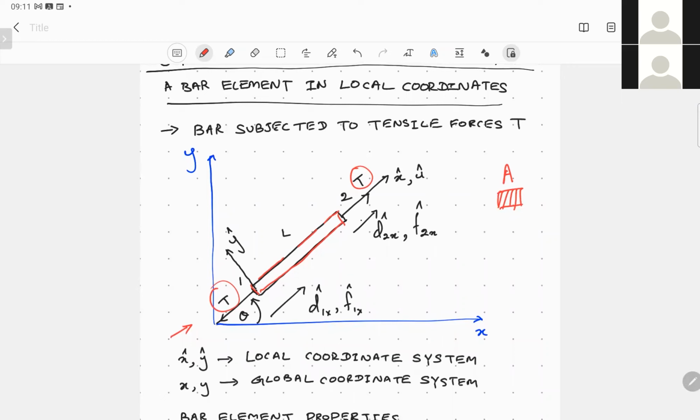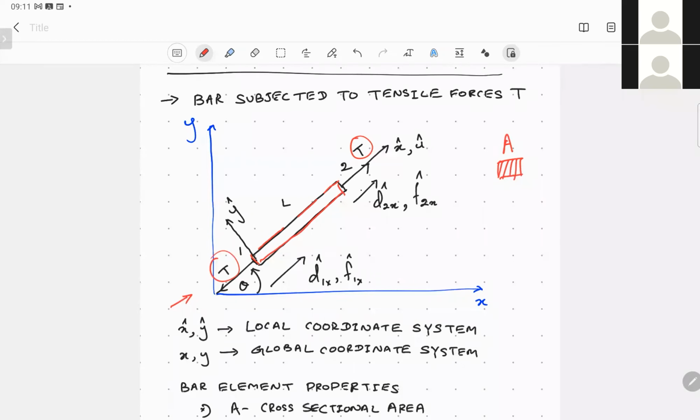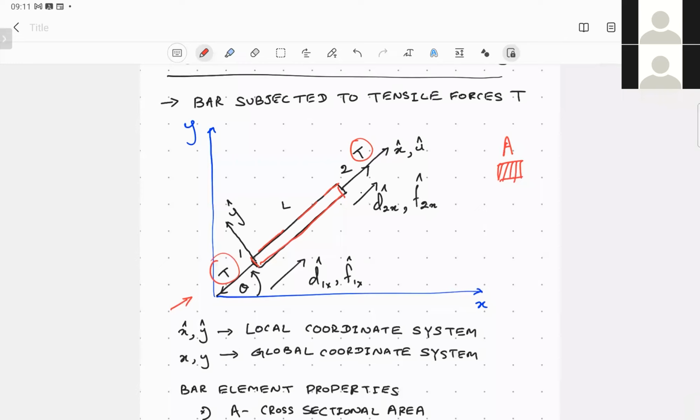So first, when we consider this truss element, we will arbitrarily place it in, let's say, two dimensions. Just like in the previous case, let's assign a local coordinate system. The local coordinate system for this truss is x hat and y hat. This linear elastic bar element is arbitrarily placed in two dimensions. In the local coordinate system, one axis goes along the linear elastic bar, given by x hat, and in the orthogonal, perpendicular direction to the length of the axis, you can define y hat.